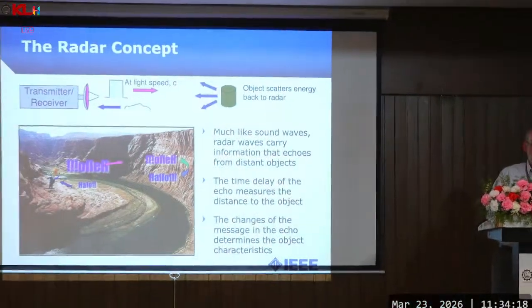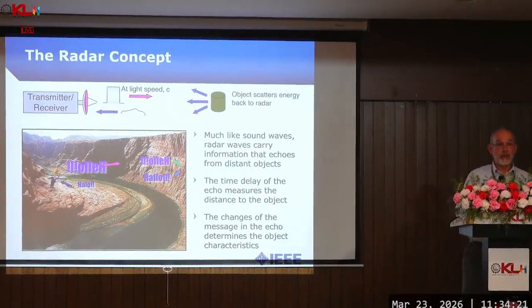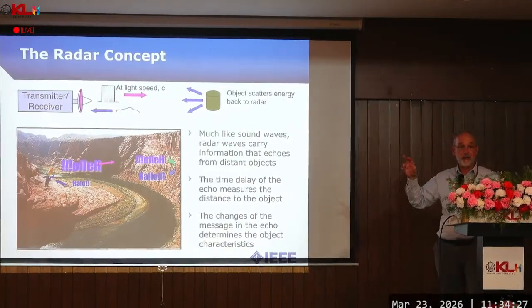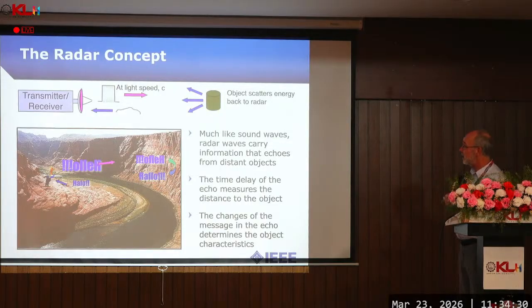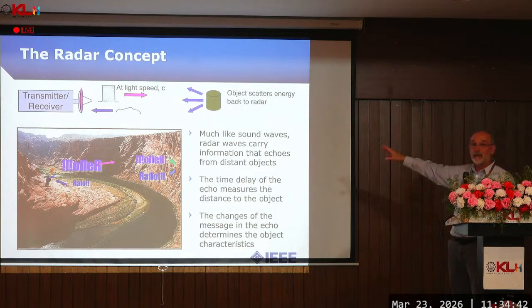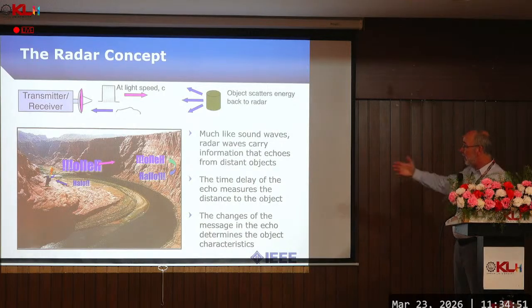We'll see. So the radar concept, for those of you who know nothing about SAR, is very straightforward. You have a transmitter, and often the receiver is located in the same electronics box as the transmitter. A pulse of energy is transmitted from the radar and interacts after propagating some distance at the speed of light with some object that you're interested in. It bounces back, some of the energy bounces back and is received by the receiver. That's the radar concept, pretty straightforward. Very much like sound waves where you make a noise, it propagates, it bounces off some material, and comes back to your ears.